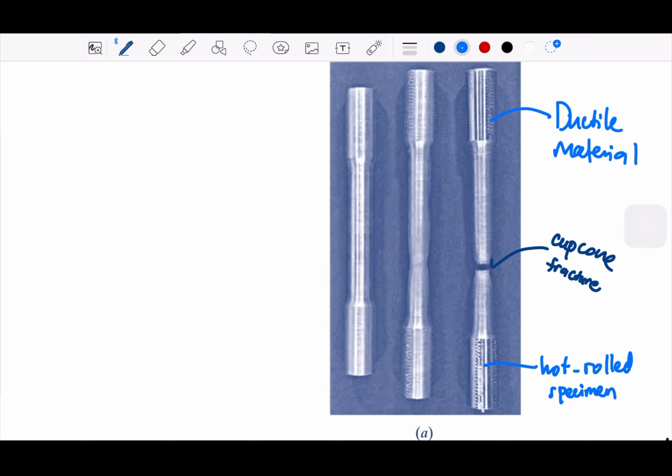We learned later how we could see the fracture. It's based on the Mohr circle, M-O-H-R, Mohr. I'm not sure how to say that, but I think it's Mohr, not "more". We use the Mohr circle to determine brittle or ductile materials.